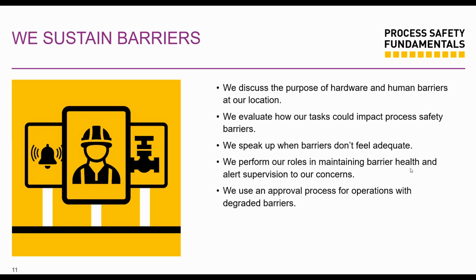Perform our roles in maintaining barrier health. We want to make sure that all our barriers are healthy. That's part of what we need to do when we are carrying out tasks, and use an approval process for operations with degraded barriers. So you have a vessel where probably one of the drain valves is not properly holding, it's not properly isolating.